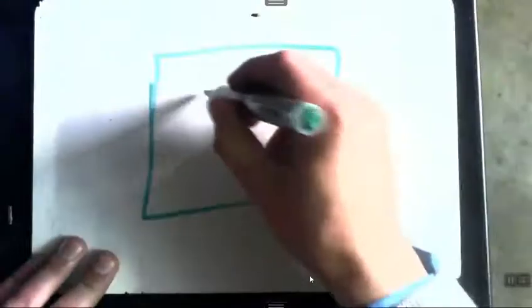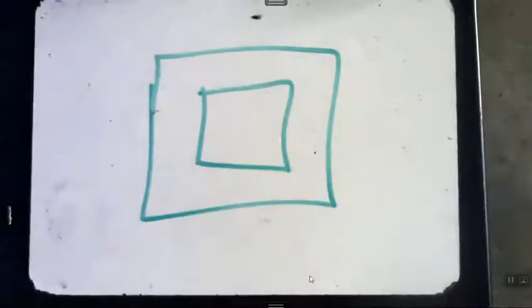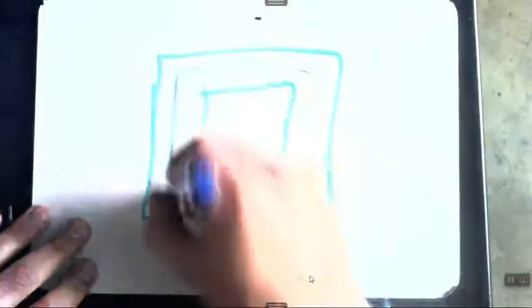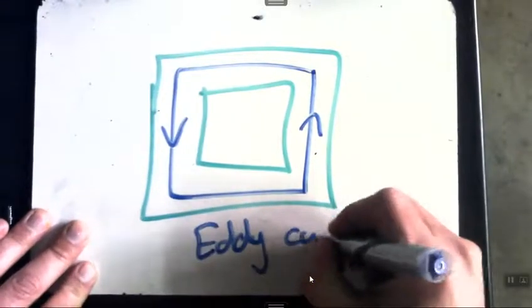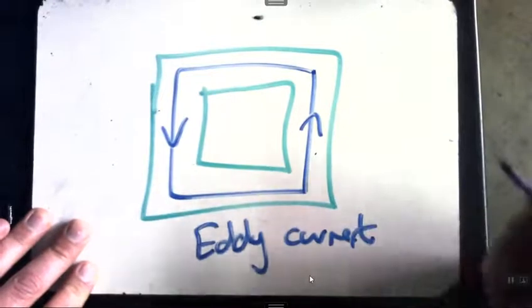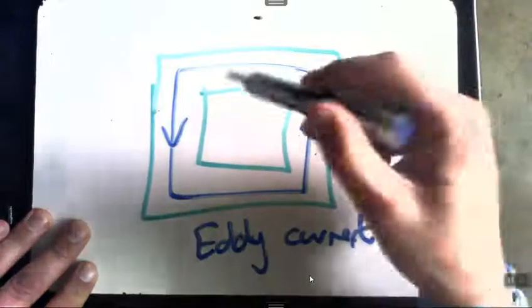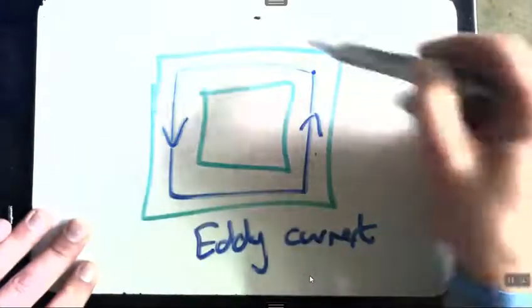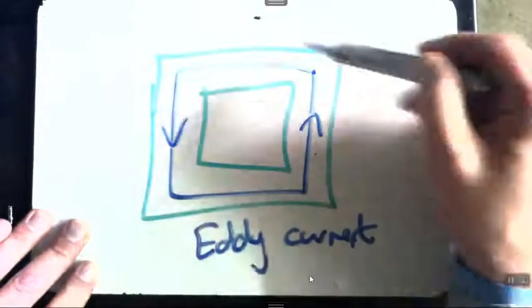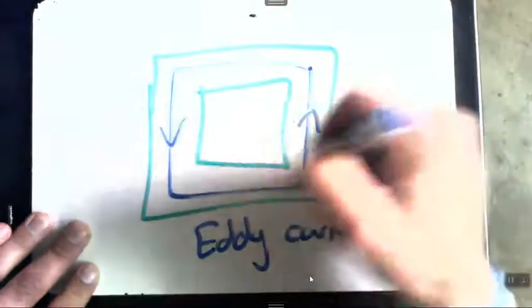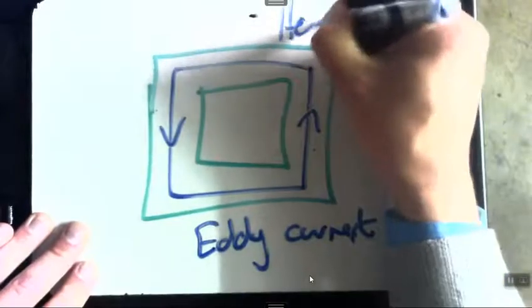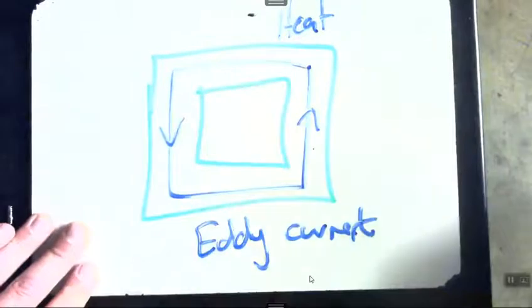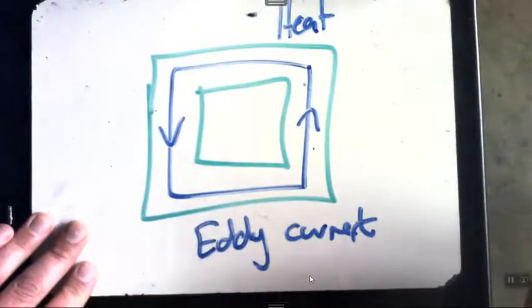So inside our metal core, as the magnetic field flows there is a current being produced through this, and that current is called an eddy current. Because there's a current because it's a conductor, that current has a very, very high value of amperes, and that creates heat. Now this heat is energy that is lost from my secondary to my primary side.